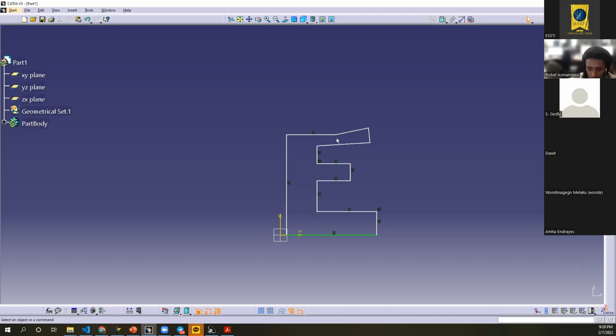You press the constraint button, and then you press the horizontal line button, and then it's horizontal. And in case you want to do multiple lines together, you press the control button, and then you click like this. In this case,